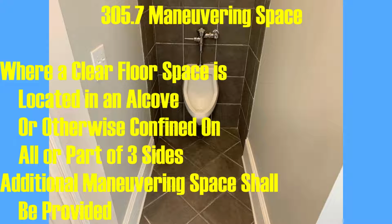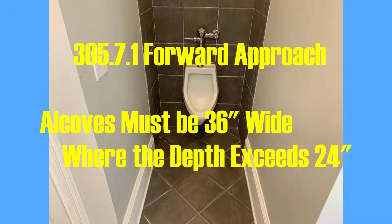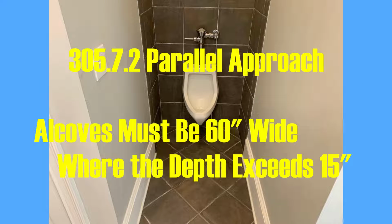Where a clear floor space is located in an alcove or otherwise confined on all or part of three sides, additional maneuvering space shall be provided at the element. Section 305.7.1 Alcoves for a forward approach in an element must be 36 inches wide where the depth of the alcove exceeds 24 inches. An alcove with a parallel approach to an element must be 60 inches wide where the depth exceeds 15 inches.